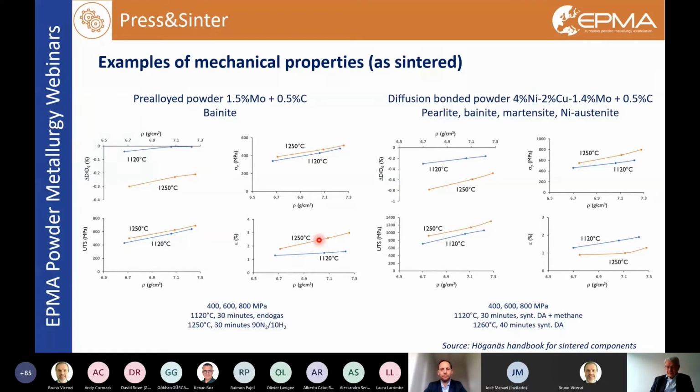So these steels have a ductile behavior, as might be expected from the microstructure. The reason why tensile elongation is not so large is because it's very difficult to let the deformation spread over the cross-section of the material, as I mentioned before, showing you the microstructure with the damage localized.